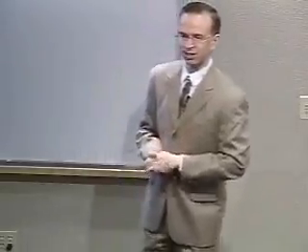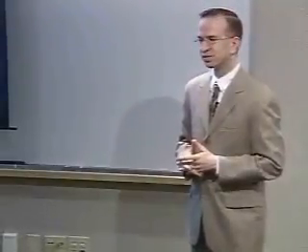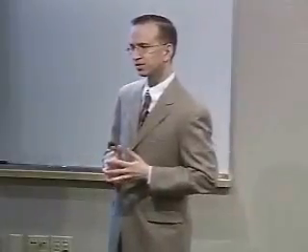That's a good question. I guess we can take this offline if this has a complicated answer, but my guess is that if you have two preambles fighting with each other, since that's specifically what the receiver is trying to lock onto, that might cause more adverse capture effects than a preamble which is going concurrently with the middle of the packet. But from your description of your test, it sounds like you're overlaying the preamble of one with the middle of another packet, since you're not precisely controlling when that interference packet starts.